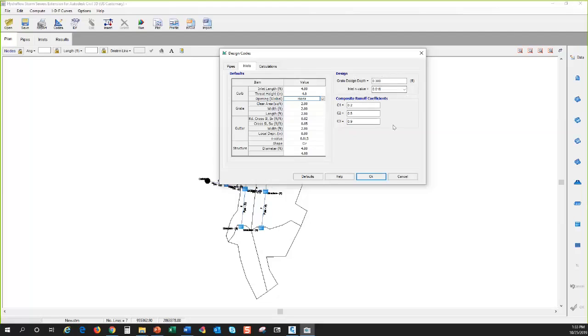And then here are your composite runoff coefficients that I was mentioning. I'm not going to change these. The 0.9, which equates to pavement, 0.5, 0.2, they're not standard values, but values that I see a lot when you're weighting the average of an area for runoff calculations for the rational equation.